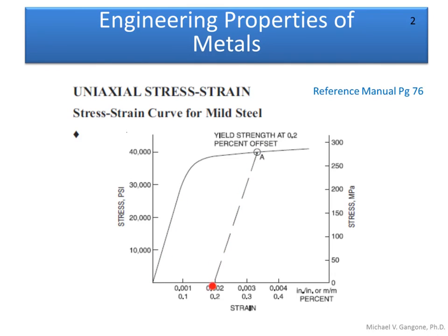And where this intersects the stress strain curve is the yield point. Okay, so this would be my yield stress, and down here this would be my yield strain. Okay, so this is how we use the 0.2% offset method. And again, I bring this up because it is covered in the FE manual, so make sure that you go through and understand how to use this method, just in case it is asked on the FE exam. So again, you have 0.002 strain, draw a line that has the same slope as this line, and where it intersects is your yield point.